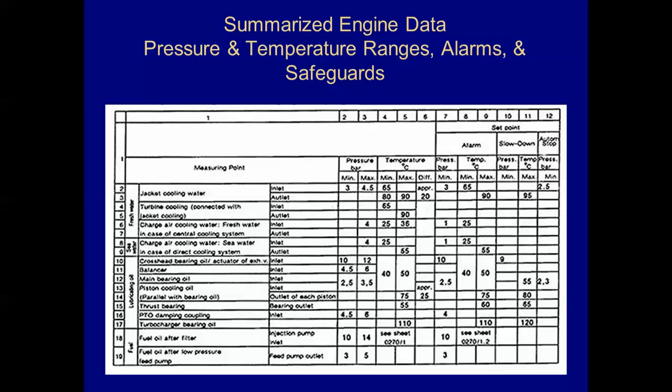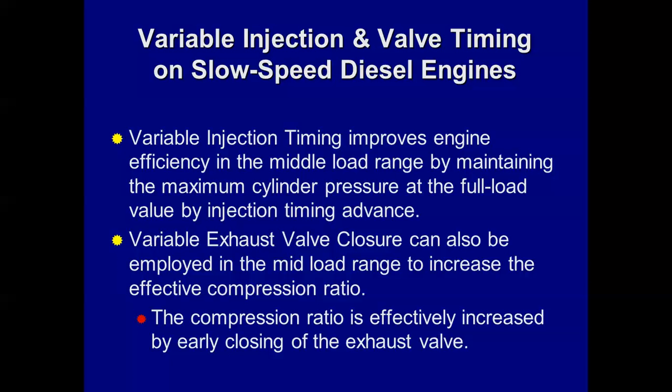And typically, on the larger engines, your load indicator, your rack setting. But the main ones are turbocharger speed, scavenging air pressure, and your exhaust temps, which are very vital to give you just a quick indication of the health of the engine.